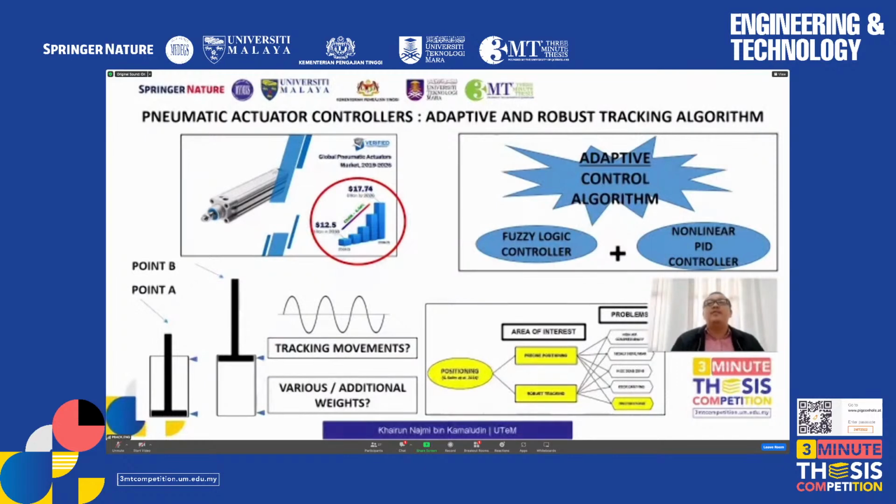Well, to start off, there's a fundamental issue. If you replace those robotic arms with the pneumatic actuator, the rider can only go to the maximum height or to the minimum point. No control in between. With innovations, behold, servo pneumatic actuator. Its integrated positioning sensor allows it to move in between, adding more flexibility.